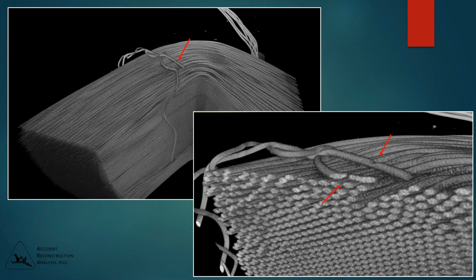the failure that we found. You can see there's an actual break in the magnet wire from the ID. And then you can see that magnet wire is doubled back on itself. And then there's a notch adjacent to the break in the magnet wire.